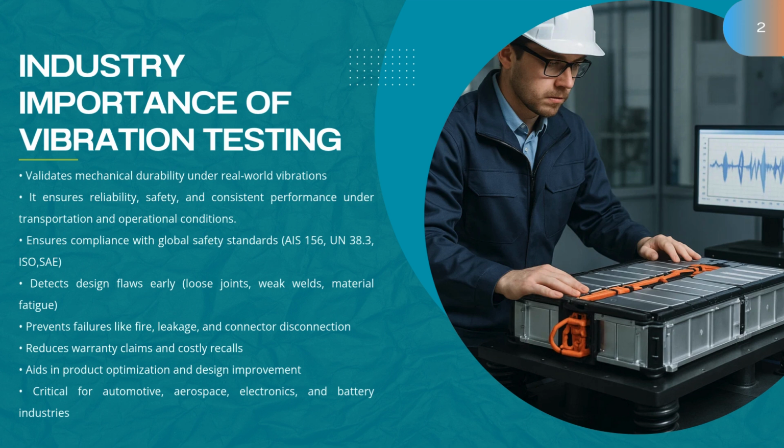It validates durability under real-world conditions like transport and operation, ensures reliable and safe performance, preventing unexpected failures, helps meet global standards like AIS 156, UN 38.3, ISO, and SAE. Detects design issues early, such as loose joints, weak welds, or material fatigue. Prevents failures like fire, leakage, or connector disconnection.